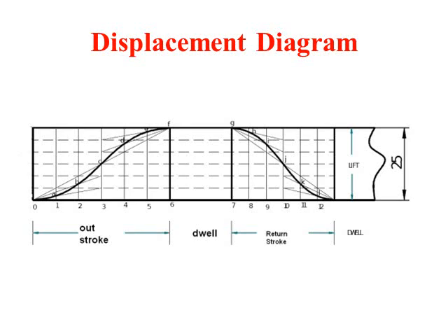After doing that, as the follower motion in this problem is uniform acceleration and retardation, to draw the displacement diagram we have to, from the center of the outstroke, take a distance equal to the stroke.